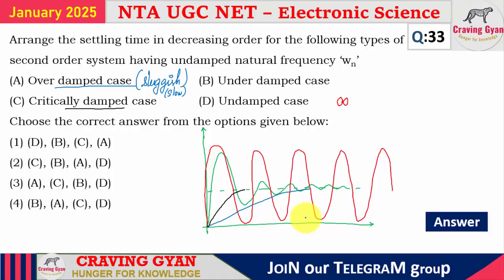Arrange the settling time in decreasing order they have given. So in decreasing order, if I am specifying, which one will be coming first? See, faster system response is which one? Critically damped systems are faster. Then it is followed by underdamped system. Then it is followed by overdamped system. Then it is followed by undamped system.